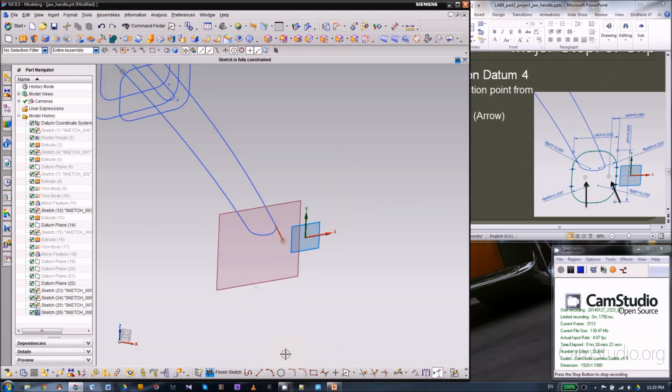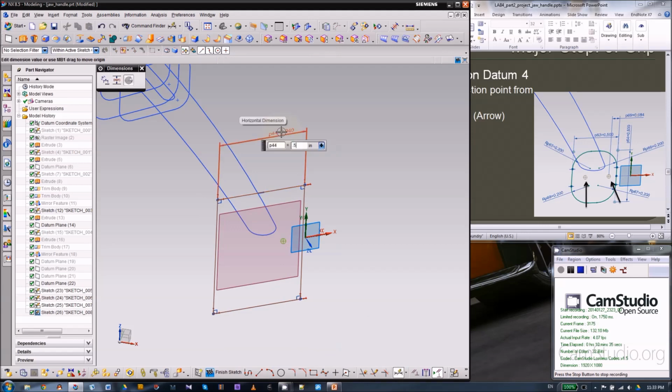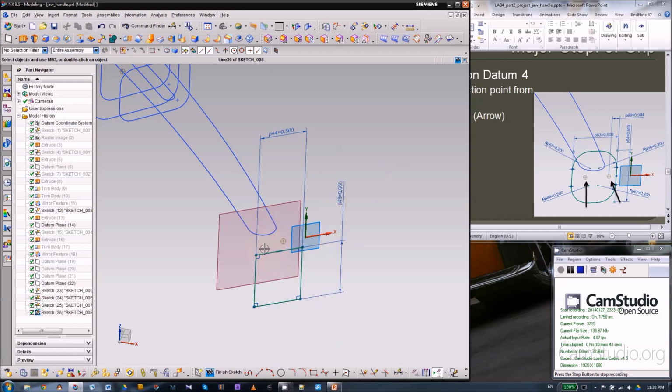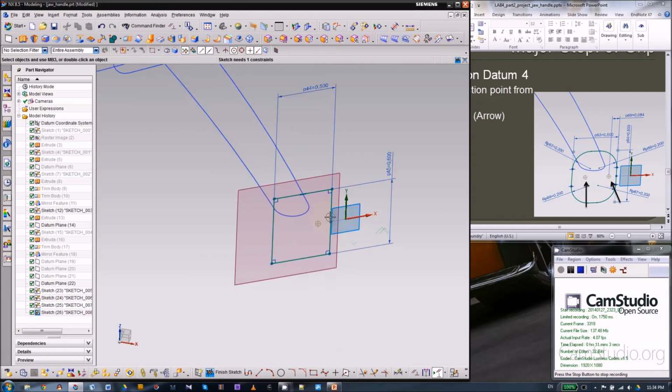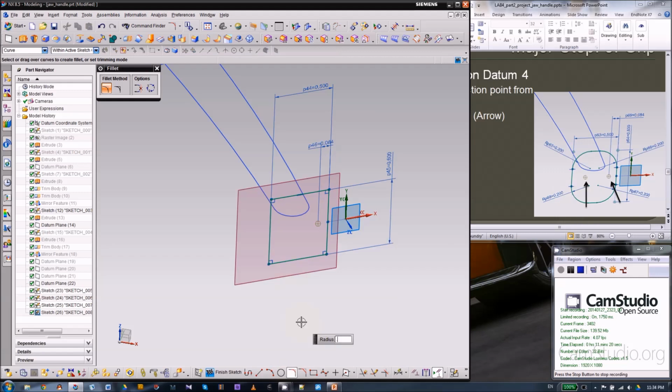You can pick this point, turn it into reference, then rectangle again, and width 0.5. Also the height is 0.6, and it's out of the point. So I'm gonna move this around. Be careful not to snap to anything on this sketch. Okay, and again, midpoint constraint from the orange to this line, to the left or right vertical lines. Then dimension from the point to the vertical line will be 0.05084. Okay, all green. Then fillet will be 0.2 in radius.